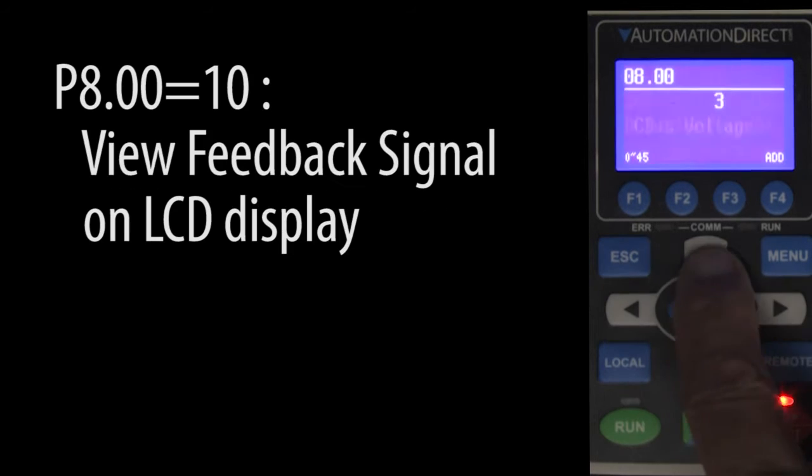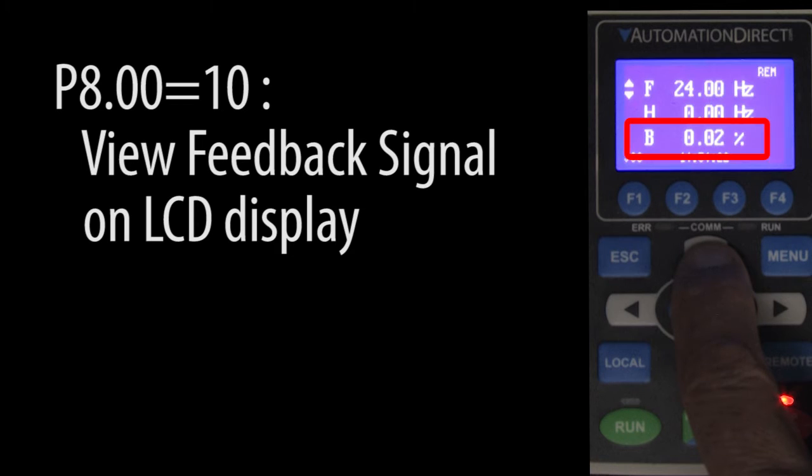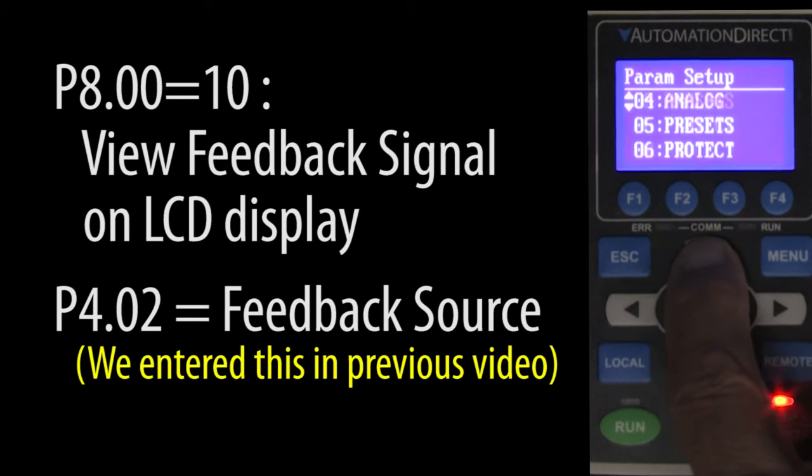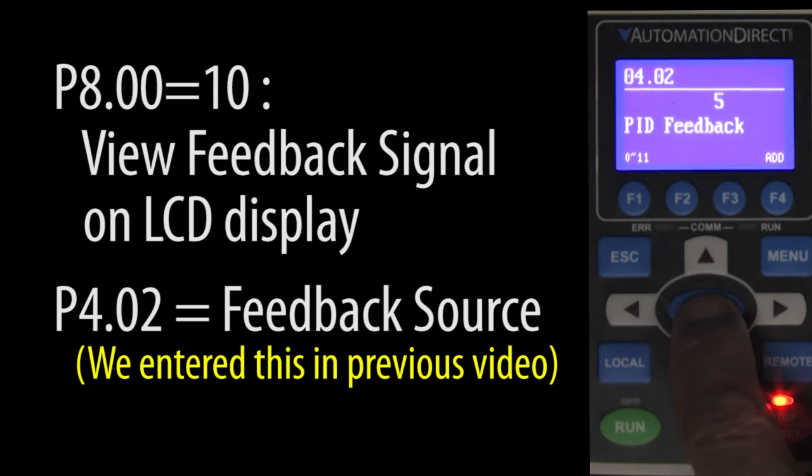If we set parameter 8.0 to a 10, we can monitor the feedback signal right on the LCD display. That's almost the same thing as the analog input we were monitoring in the first video, but this shows us the feedback signal we selected for use with PID, which is great because we know analog input 1 is working from the first video, so if we don't see it working here, we immediately know we selected the wrong function for analog input 1 in parameter 4.02. Yep, analog 1 is definitely the source of our feedback signal, which we also call the process variable.